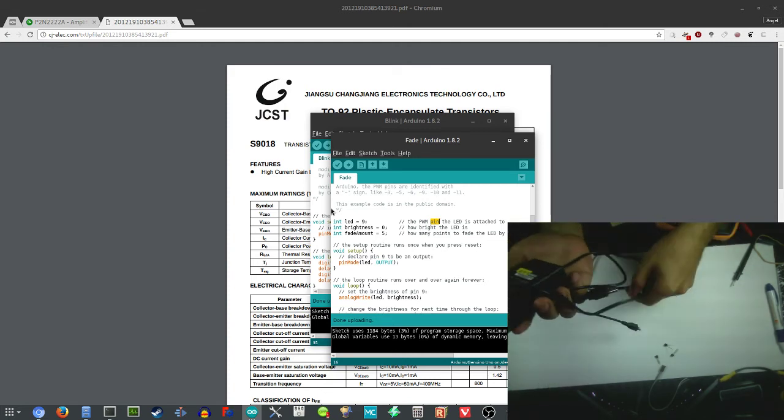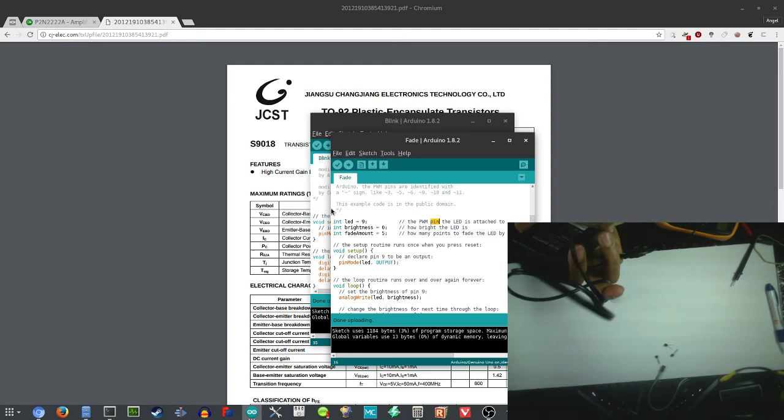And actually the transistor worked pretty well, because I guess it wasn't getting to its limit. It was really below its limit, but at the same time it was higher than the threshold voltage in order to be actually on.